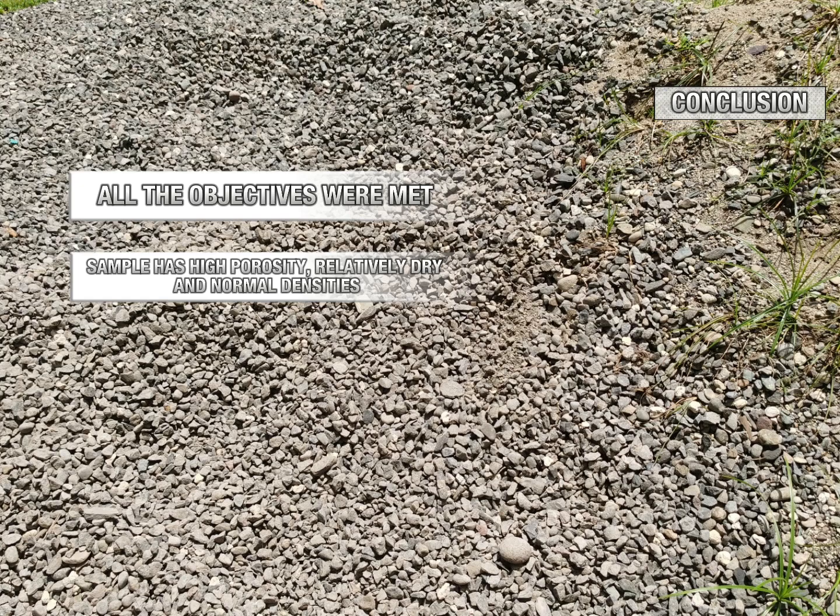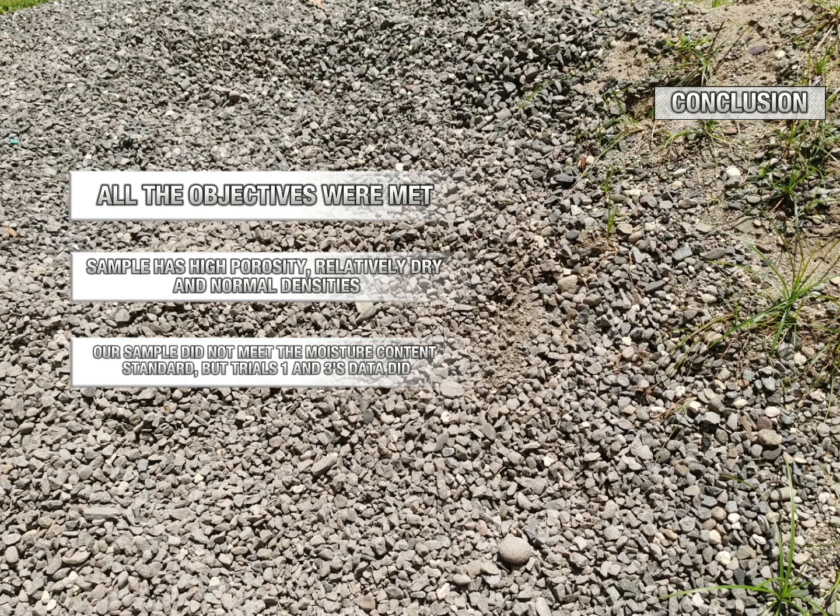Furthermore, for the moisture content, our average did not meet the standard, but trials 1 and 3 produced data that is less than 2%, which is a perfect sample that will prevent large variations of water in the concrete mix during the production.